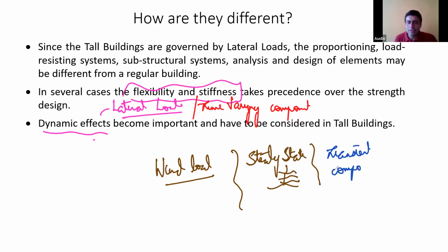There can be a transient component of your wind, or what we can also call the gusting wind. Gusting wind means a wind event which will last for, let's say, a very short 2, 3, or 4 seconds, and which will have a higher speed than your steady state wind. Have you ever felt like that?